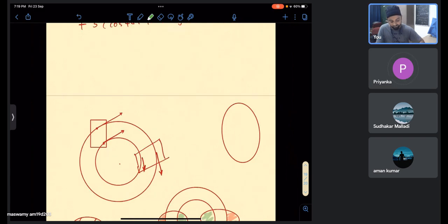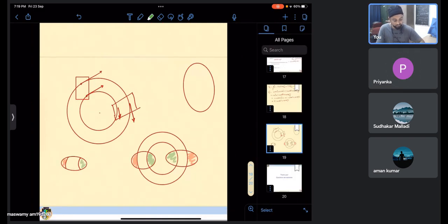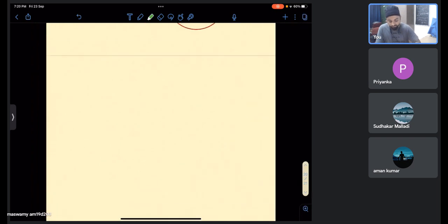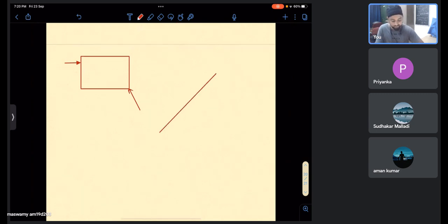Yeah, okay. No, no. See, no need to confuse both. What the professor meant is, if you have this and then you apply a force here, and if your resultant has reached the peak, it cannot go beyond the physical boundary, then you are reaching the limiting condition. This is point A, let us call this point B, and we have a force applied here. A weight of the ladder is acting. Both the surfaces have friction. That's what is said. So if you are to tip it about point O, there has to be loss of contact at point A. You agree?